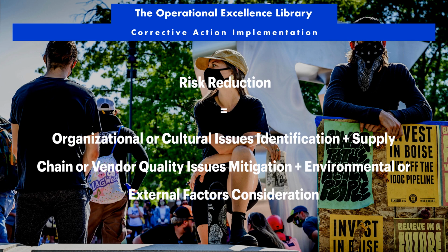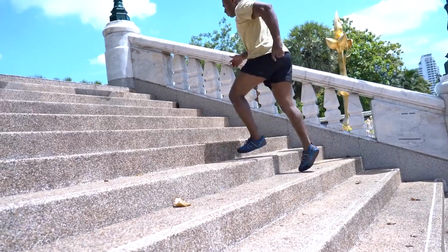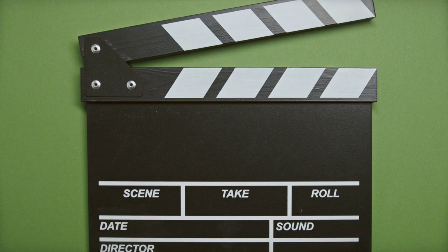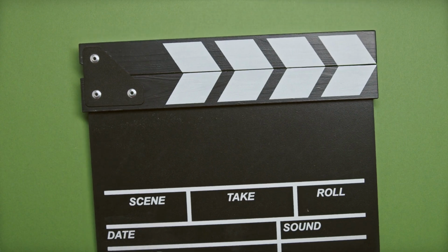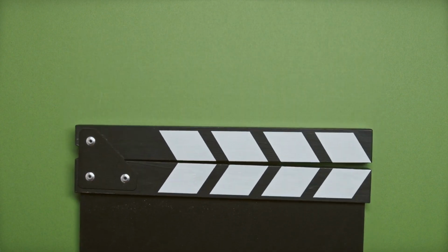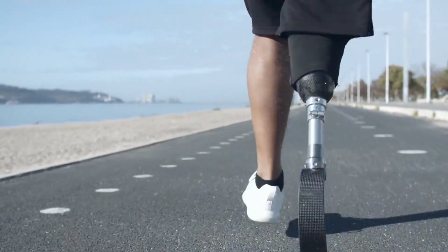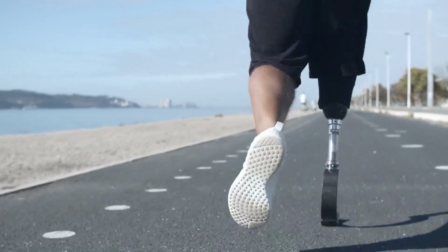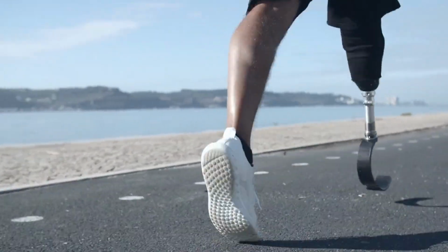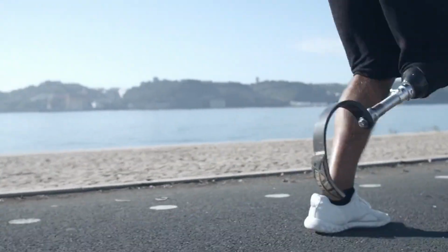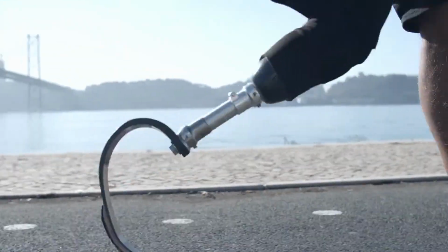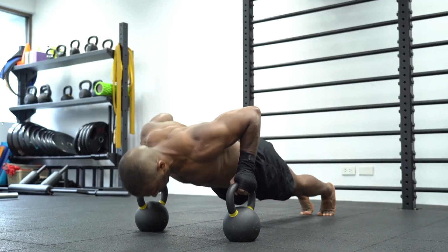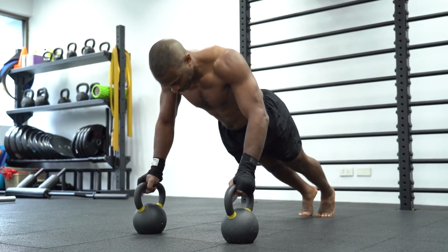cause analysis, RCA, a methodical approach to identify the underlying causes of a problem, using tools such as fishbone diagrams, 5 whys, or SWOT analysis. Failure mode and effects analysis, FMEA, a proactive approach to identify potential failure modes, assess their impact, and prioritize corrective actions. Fault tree analysis, a logical and systematic approach to identify possible failures or errors in a process or system.